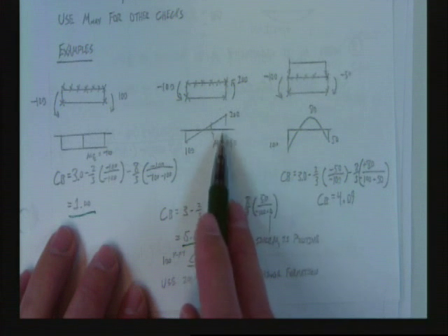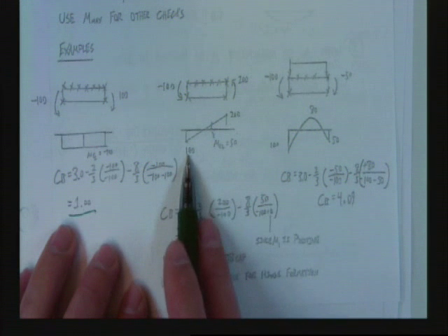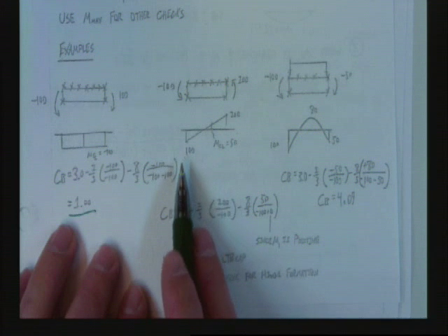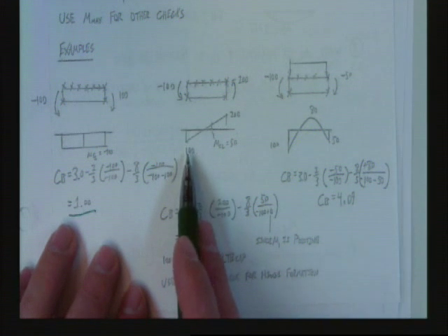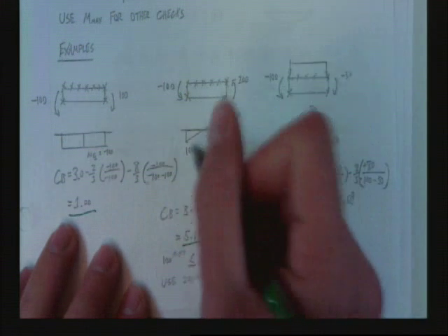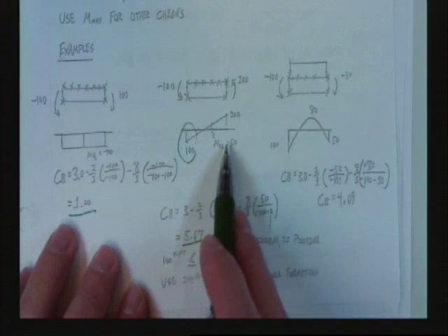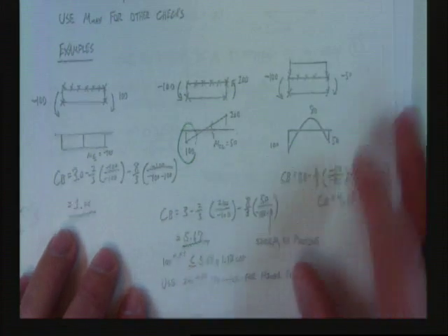Still have to check that for phi M sub P. But for lateral torsional buckling, check it versus 100. You don't get to just disregard plastic hinge formation in other parts of the girder. What this allows you to do is check for this to cause lateral torsional buckling issues, and the rest of the girder for other things.